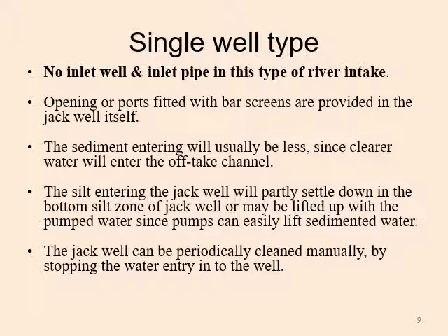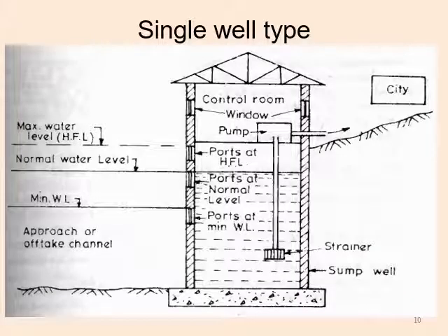If there is much more silting or sedimentation in the jack well, sometimes we have to manually stop the entry and clean the bottom zone of the intake well, or sump well, so that more water can be stored here.